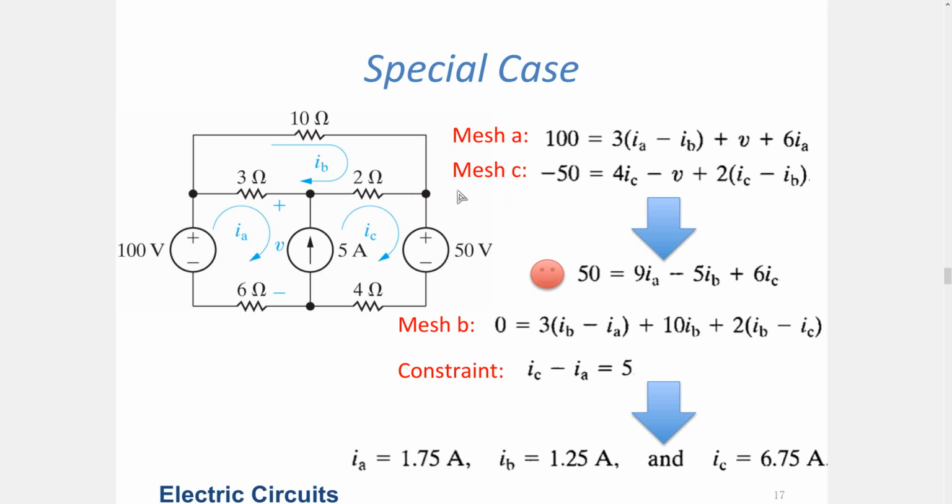So what is the good side? You get rid of the unknown variable, and instead of two equations, you write one equation, and another equation will come from this mesh, and you will deal with two equations instead of three. This might not sound like a great improvement, as we already have MATLAB to solve things, but in complicated circuits, this reduces the computation steps, so it can help.